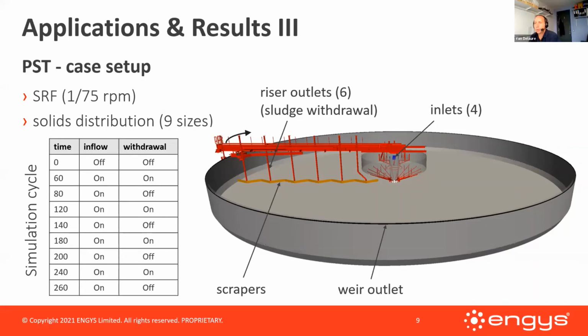Can I ask you what's the rough size of the mesh in the core compared to the overall diameter? The diameter of the whole tank is 42 meters, and the smallest cell size at the bottom, because I have to resolve the boundary layer, is 3 millimeters. Okay. So it needs a steep grading and some meshing techniques to reduce the overall cell size, because it's obviously not possible to resolve millimeters throughout the whole tank.